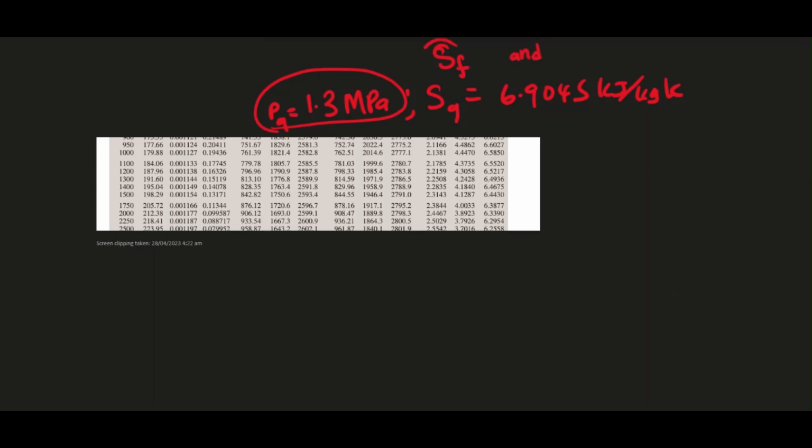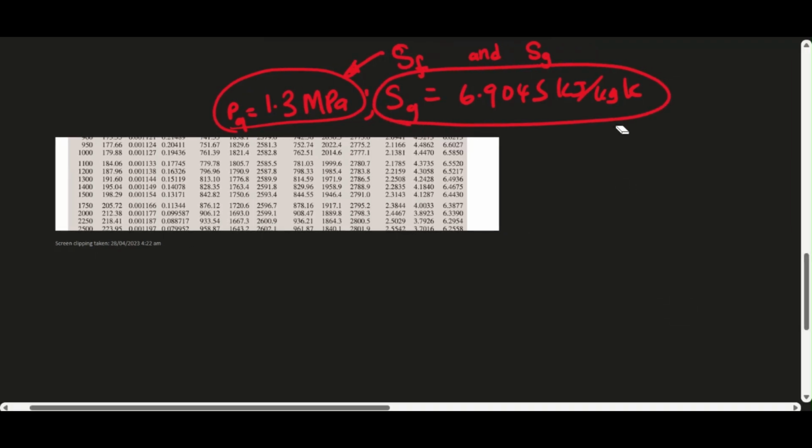Of course, the minimum is SF, and the highest is SG at this pressure, and I see if my entropy value falls in that range.